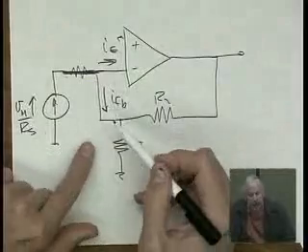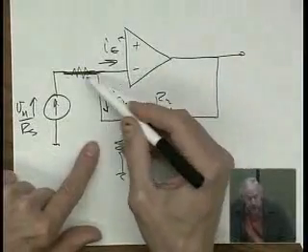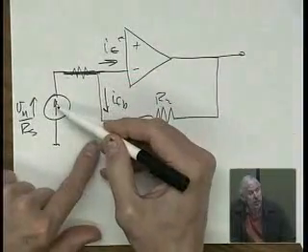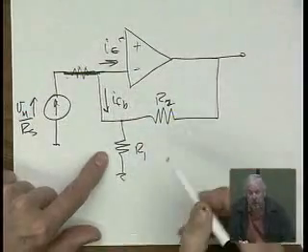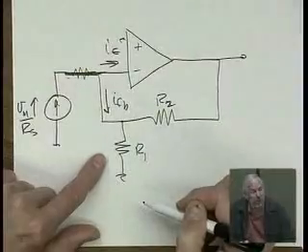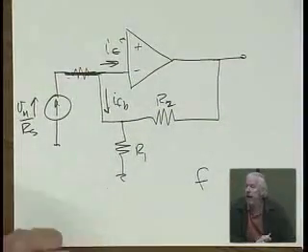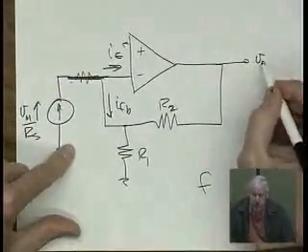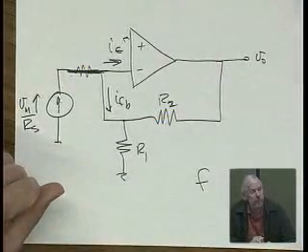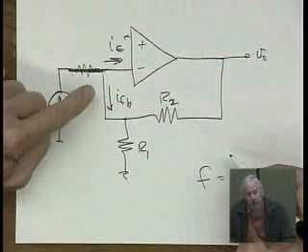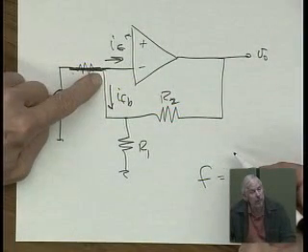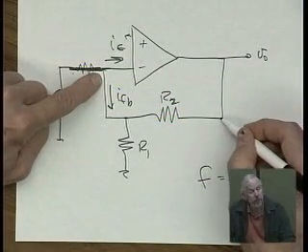So now it's really clear, right? This is a difference. It's the feedback current in shunt with the input, and all this is the feedback network. What is the feedback factor? This is V out. How do we figure it out? We short the output and drive the input.